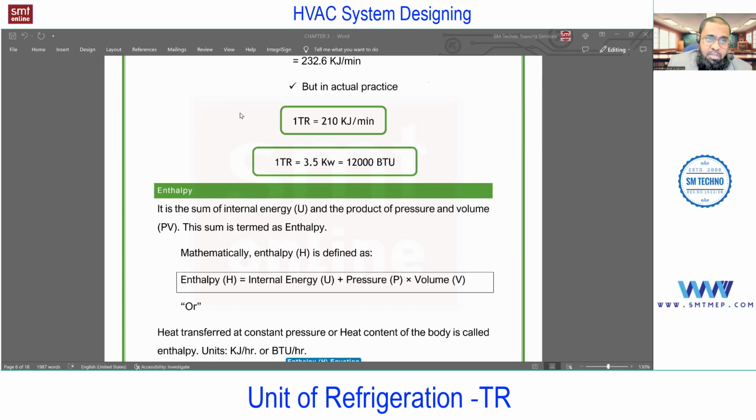In case of chiller, the case is different. The chiller starts with 0.7. Again, in chillers, we have high-class chillers or standard chillers, etc. So that range will vary. Yes, sir. From a coordination point of view, 1.2 to 1.4. Yeah, because the electrical engineer is always asking about the electrical load of the HVAC. You can consider in between 1.2 to 1.4 for a DX system. For a chilled water system, it is going to be different. Next, so I think you got the idea.